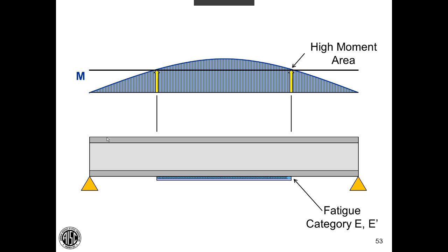Okay, that's a great question too. And yes, the loads in the weld are primarily shear, and I'm going to try to use my cursor here. Once we add in the cover plate, the stresses in this area get to be very low, but the challenge here is where it terminates.